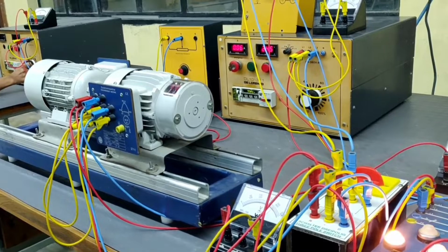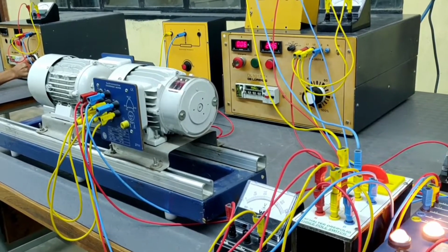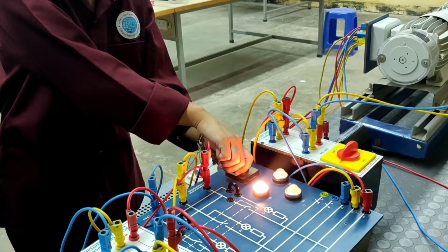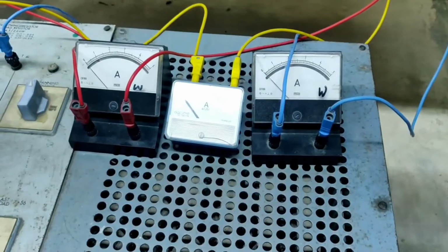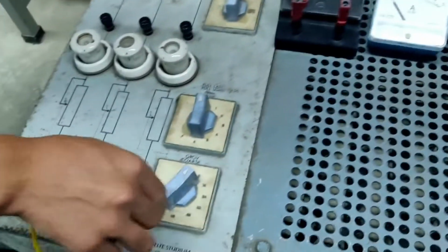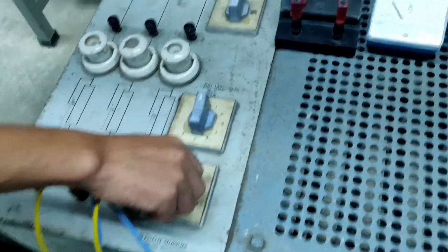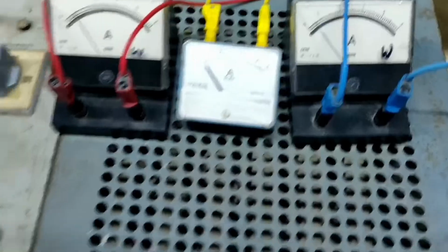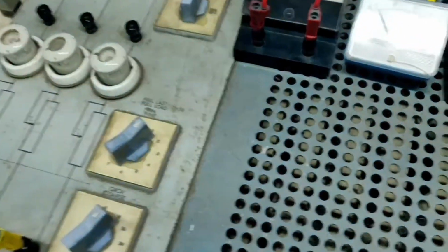After reducing the speed of the rotating lamp, we turn on the synchronization and increase the load. And look at the readings from these three ammeters connected to three different phases.